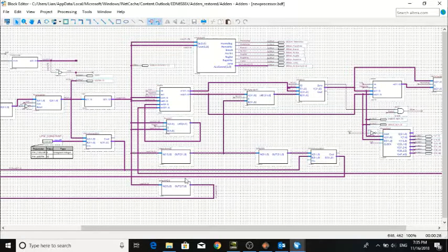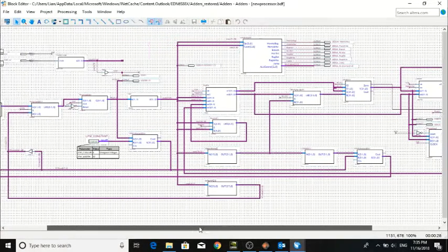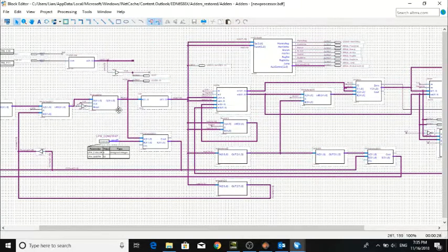The sign extend just takes in inputs and copies the sign bit to make a 32-bit output, while the left shift multiplies the number by 4. The ROM file contains the set of instructions used to run the program. These instructions are used to control address and data values, including the opcodes and functions for the control unit.